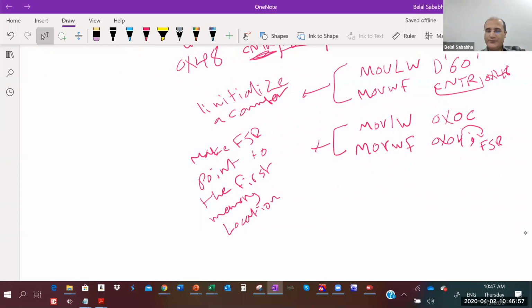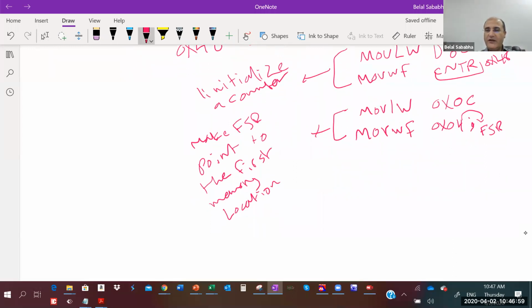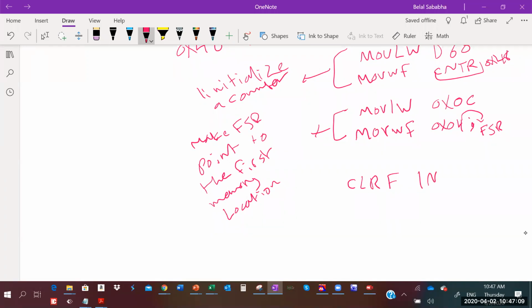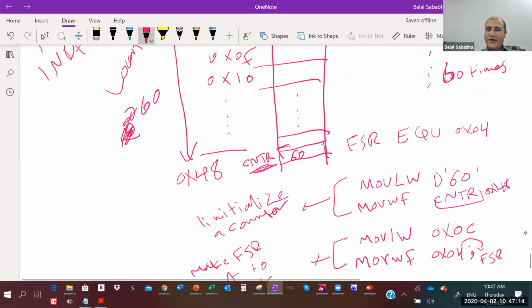Then what we do, we say clear F. What do we do? Right. 0x00. Exactly. INDF. INDF equates 0x00.